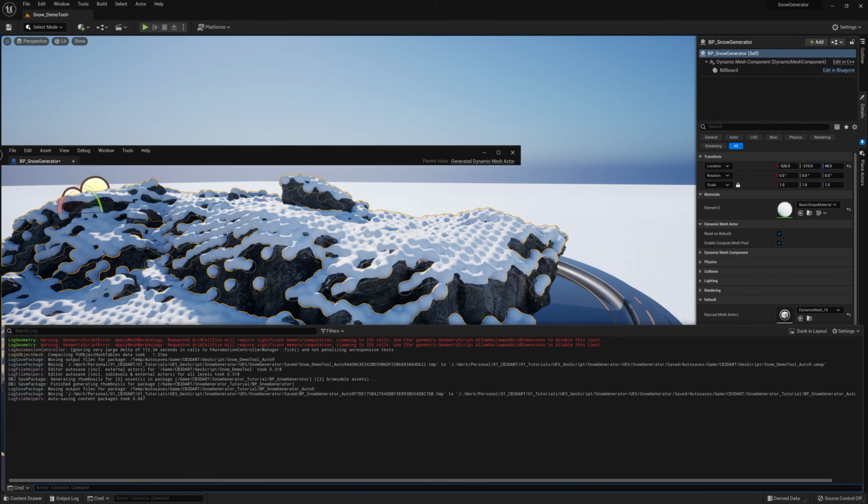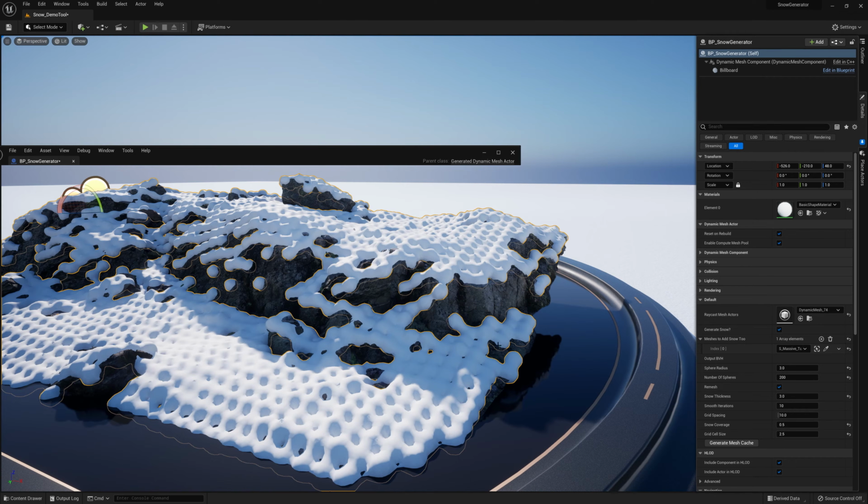and then you go into your command line and paste that in and press enter, you'll see that it's set to false currently. But if we were to change that to 1, now it's set to true, which will basically allow us to generate any size of voxel. You have to be very careful with this. You could end up with millions and millions of voxels being generated, and this could literally crash your editor, possibly your computer, your graphics card. So just be very careful with this.